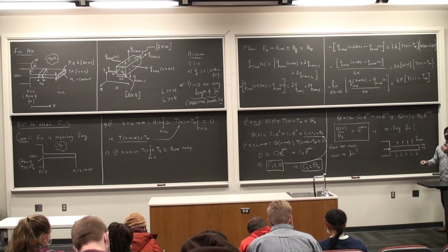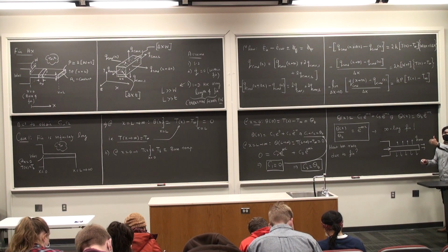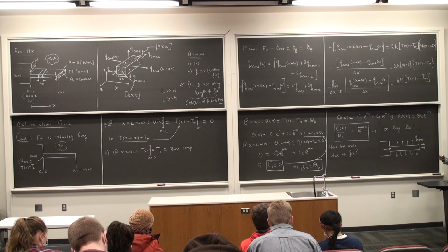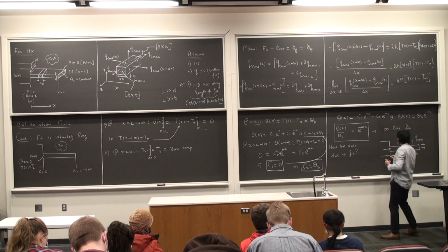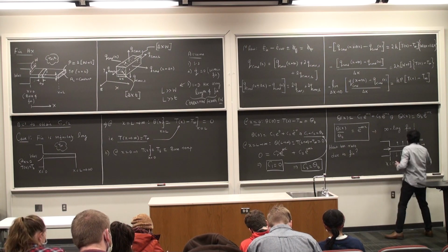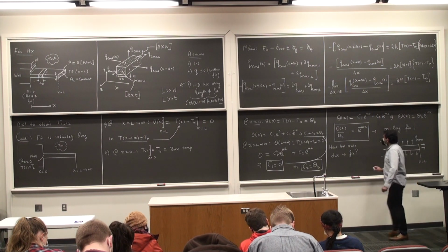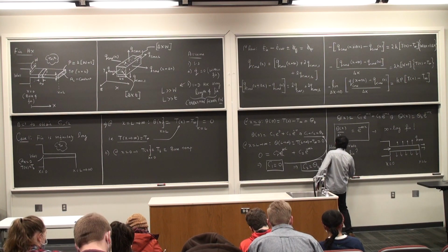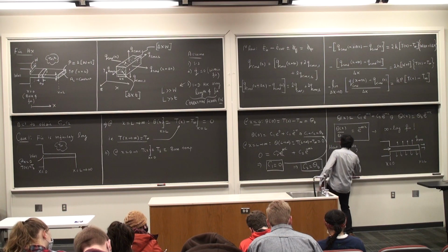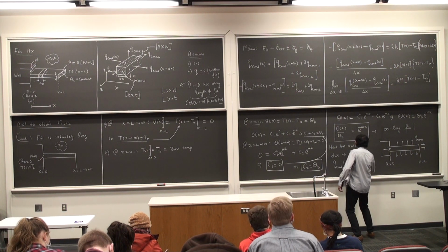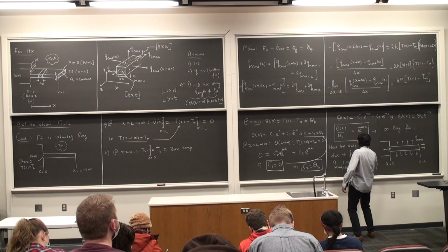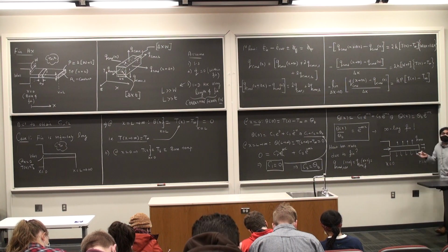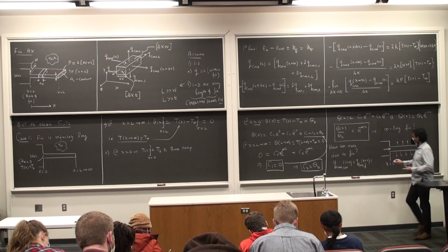I'm going to have conductive heat transfer from the wall onto the fin, and the conductive flux from the wall is the same as the conductive flux into the fin at x is equal to 0. So this is x is equal to 0. This is x is equal to L. So I want to say that Q conduction, the wall, at x is equal to 0 is the same as Q conduction of the fin at x is equal to 0, and because there is no energy generation taking place, this is equal to Q loss.